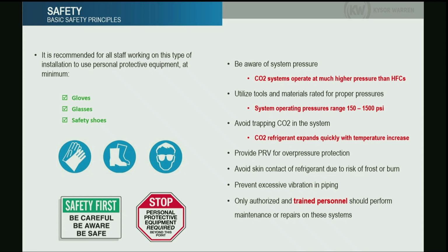The other thing about CO2 that we need to be aware of is that CO2 expands really quickly. It has what we call a high coefficient of expansion. So if we have CO2 liquid trapped in a part of the system that has no way to release or escape, that can increase the pressure really quickly if the temperature increases as well. And that can actually break the pipe in some situations. We have seen that happening. So it's very important to make sure that you do not trap CO2 in any part of the system.